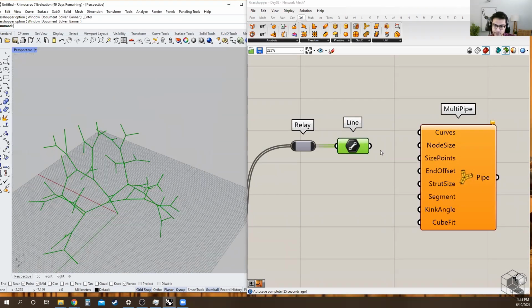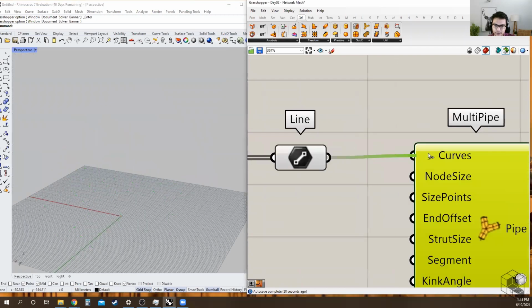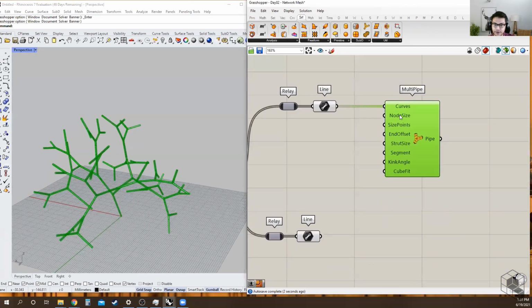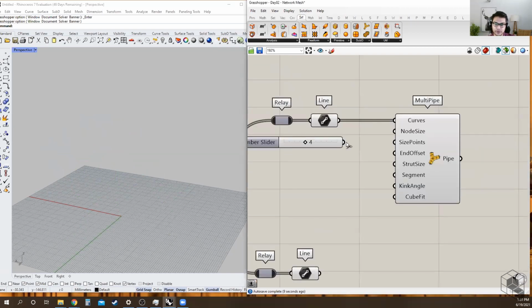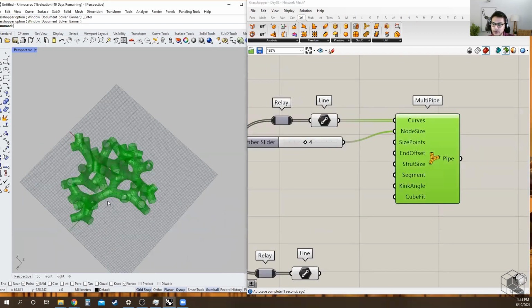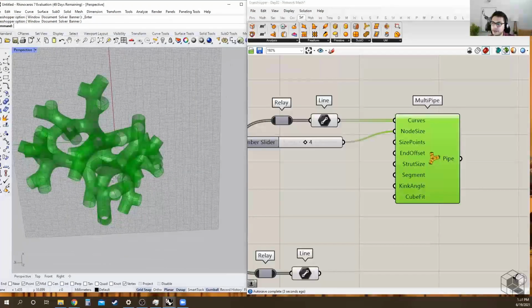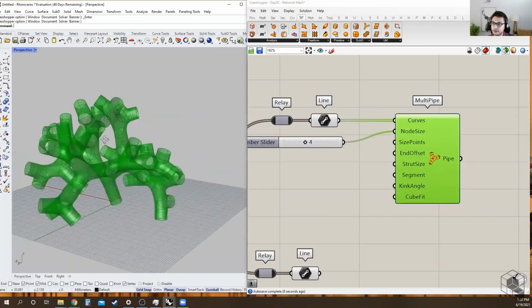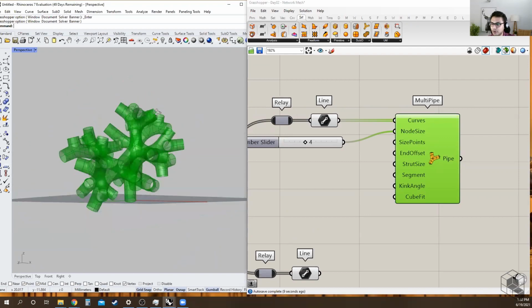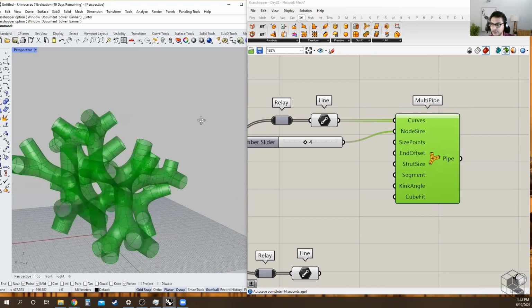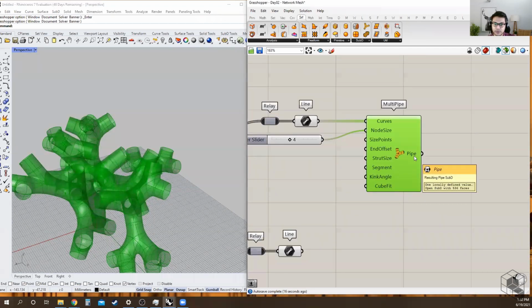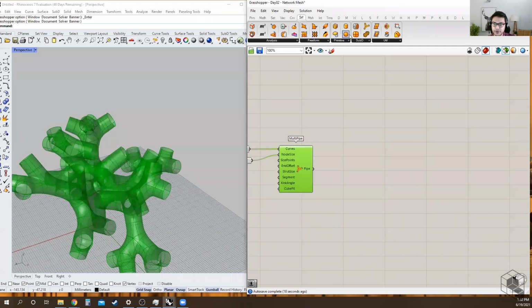much easier. So the way it works is that you give it a curve input, you define the node size, which is the radius. I'm going to use size 4 because that's the size I used while defining the loop. And that's the sub D model that I have. Now, don't confuse sub D for a mesh model. They are two separate things. But once you have a sub D pipe, you can convert the sub D into a mesh.